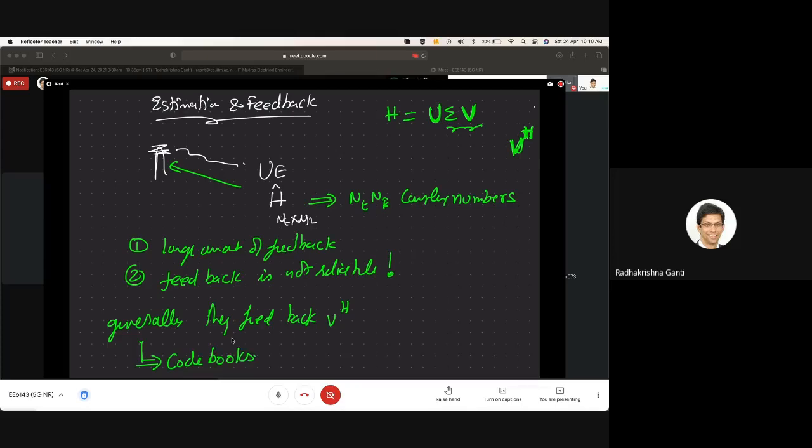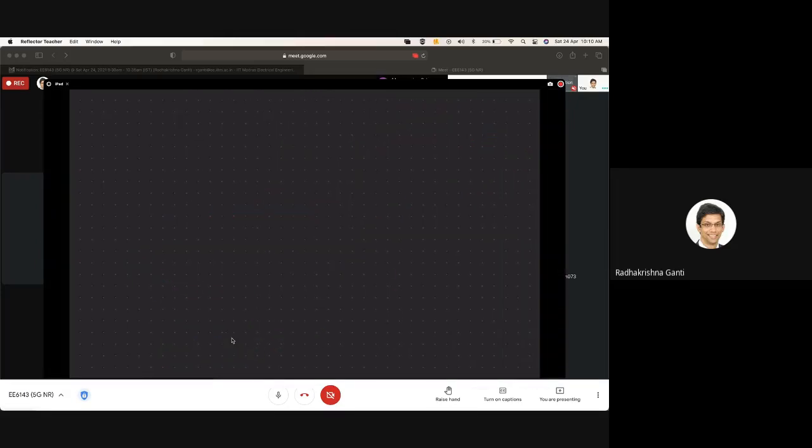So what is a code book? Let us understand this with a simpler example. Suppose we take the case of a SISO channel, Y is equal to 0.2567x plus noise. I'm just giving a hypothetical example. The UE somehow estimated that my channel is equal to 0.2567 exactly. Let's not worry about how. Now you have to feed this back, up to four decimal places. This is a painful thing.